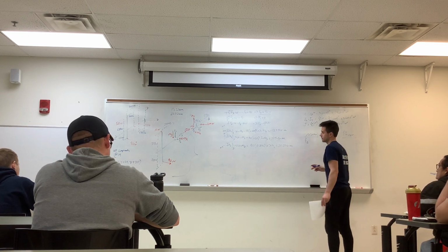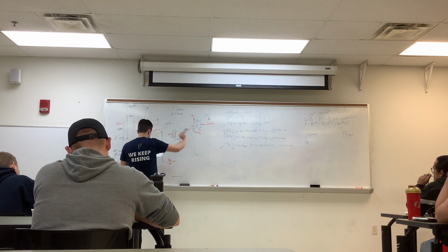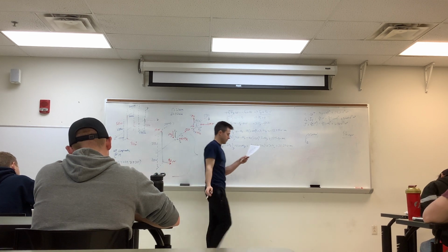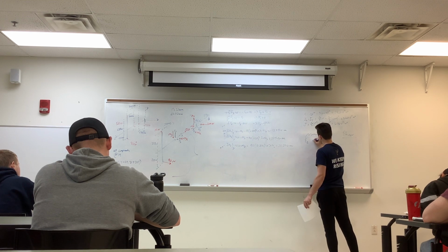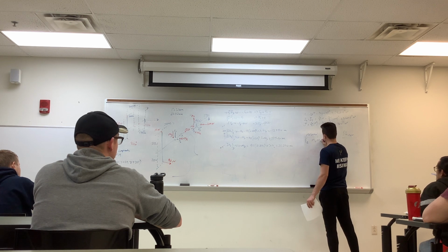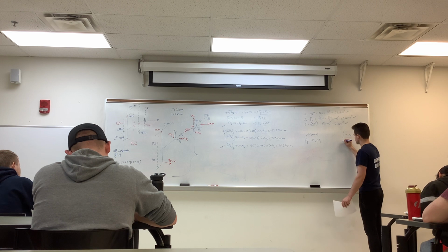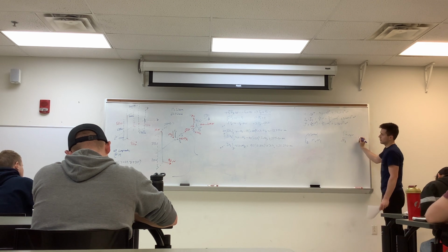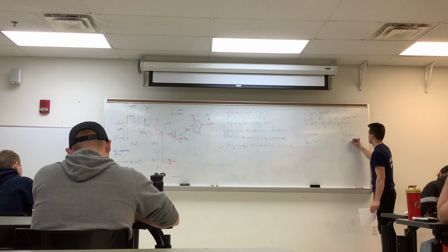And our two separate moments, our moment about x and our moment about y, will also cause normal stress. And what causes shear is our torsional moment, in this case our moment about the z direction, and our different transverse forces, so F of x and F of y.